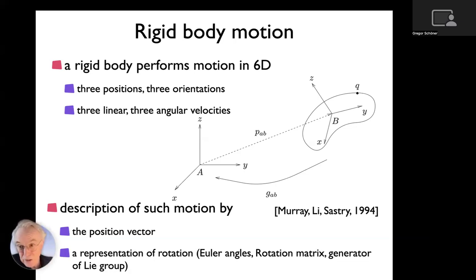And the rotation matrices have many more entries than just these 3 angles. And they are actually not independent, therefore, and there are various ways of combining these 2 sorts of things. And actually the most advanced way of doing that, that is, for instance, espoused in this book, is to generate different rigid body configurations from a Lie group. So a differential description where you just say how you reach a neighboring configuration by having a continuous set of transformations.